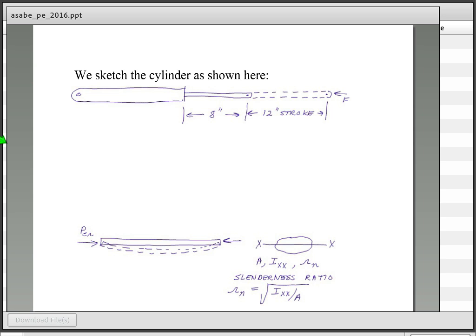And ordinarily, in a case like this, if the thing is at full extension and you've got some major load that it's pushing on, you run the risk of having buckling failure in the rod itself. Probably would not have buckling back in the cylinder itself, but in the rod, it's much more slender and lengthy.